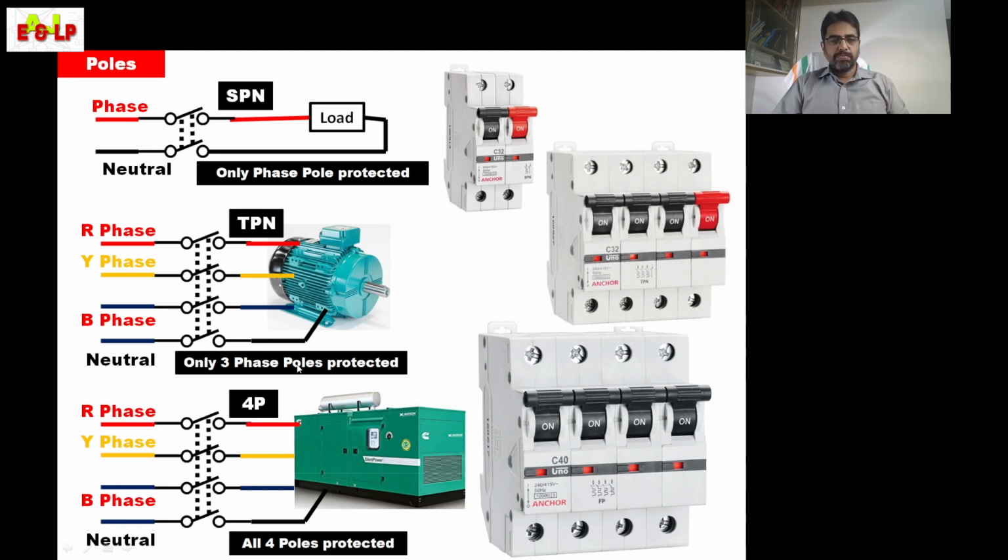Next is four pole, means four poles are there for three phases and neutral, and all the poles are protected. It is used for generator or emergency circuits to isolate all the terminals, means all three phases and neutral will be isolated for protection. In such cases we can use four poles.